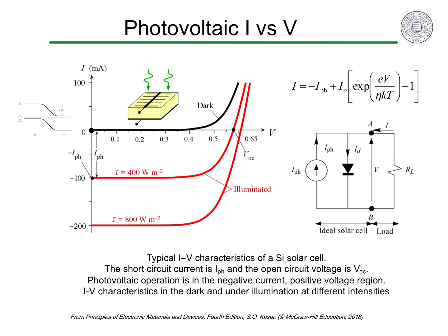The electron and hole pairs separate and create a current in the reverse bias direction, here shown as a negative current like a diode in reverse bias. Thus the short circuit current is negative and proportional to the light